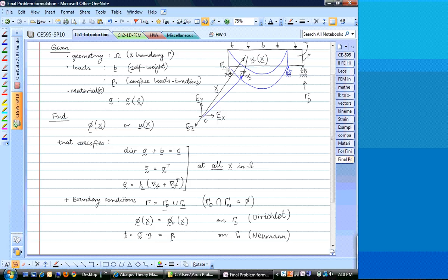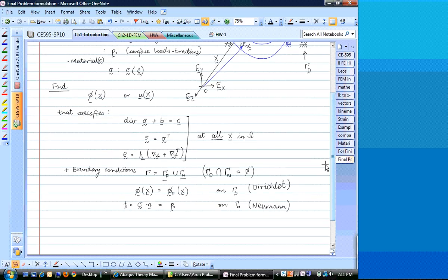So yeah, one example for a specified function on the boundary is 0, where no displacement takes place. In this case, one component or two components of this bridge, if it's a three-dimensional thing, are set to be 0. The third component along the x direction is free. So you can have parts of the components of your map also to be specified.